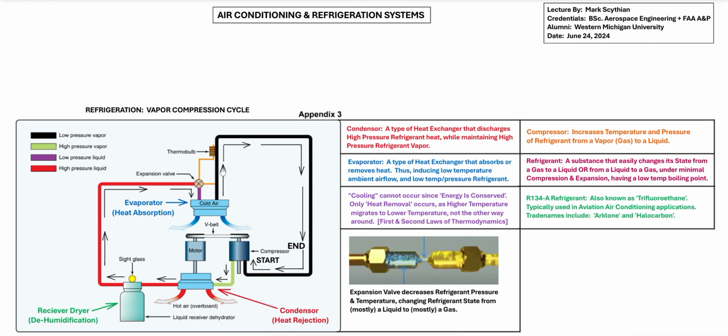Thereafter, the refrigerant continues to flow, and it starts to revert from a liquid more into a gas, partially liquid, partially gas. And by the time it is almost back to the return state of the compressor, it has reached a pure gas. You don't want liquefied refrigerant entering the return side of the compressor, as this may damage or destroy the compressor. So that ends the cycle and it starts back over, and we have this sequence of gas to liquid, liquid to gas with the refrigerant, and then we have the cycle of heat rejection initially and then heat absorption finally. So this is the whole premise of heat removal rather than so-called cooling.